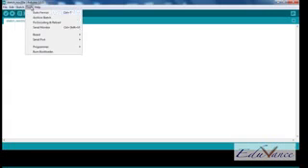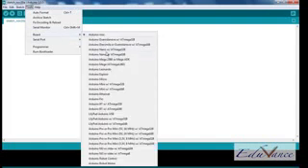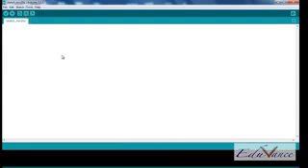Remember in lecture 1 I had discussed that the compiler needs to be called in to convert the basic program into something called the hex file. The tools folder here is a fairly complex option where you can select the kind of board that you have. As I said, Arduino has different kinds of boards. The board that I discussed as part of lecture 1 was the Arduino Uno board, and if you have different boards you can select that. What that does is that your Arduino compiler understands how to convert the program written here for the board that you've selected.